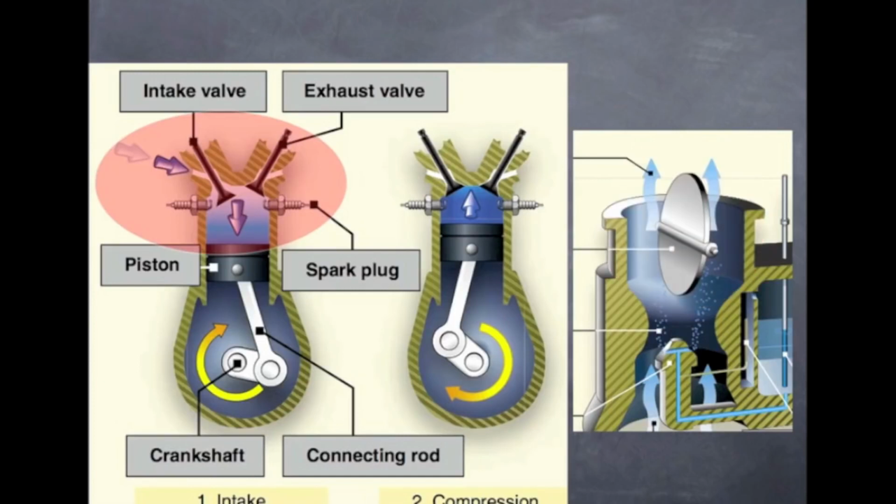So again, we look at our intake, and we've already changed our throttle setting. We changed our RPM, and now we have less air being pulled through into the cylinder because of less RPM. Therefore, the manifold pressure would actually go up. And we know that because the manifold pressure is measured in the intake manifold.